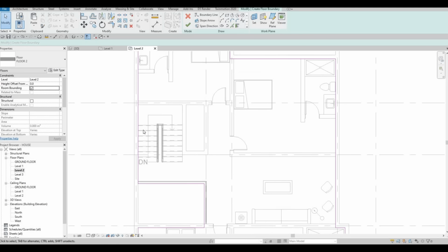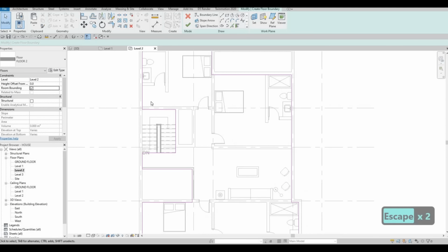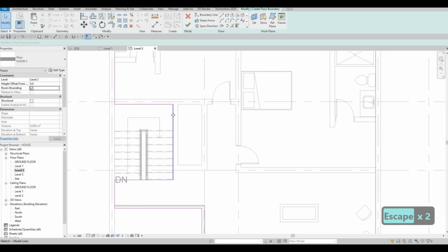So now we need to create an opening onto this area as well for the stairs. So now what I'm gonna do is I'm gonna go around here, SL again, and then TR, trim and extend onto this area. So now we have that opening right here, and then we have this one right there.